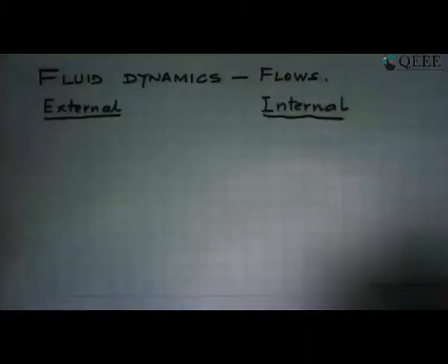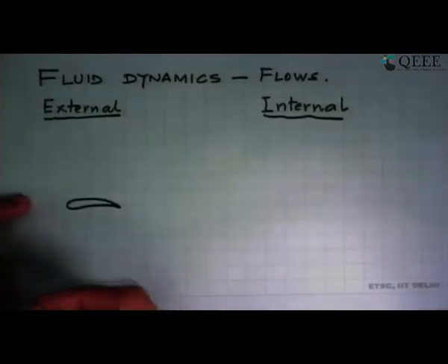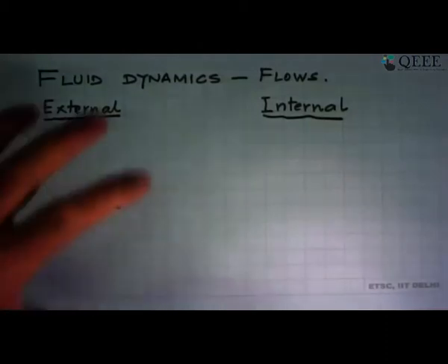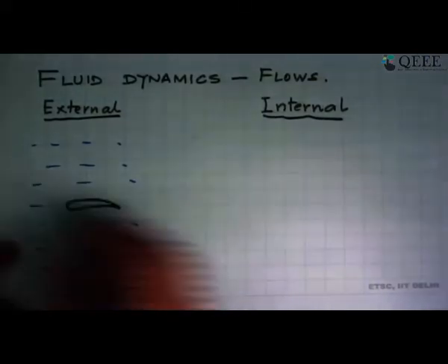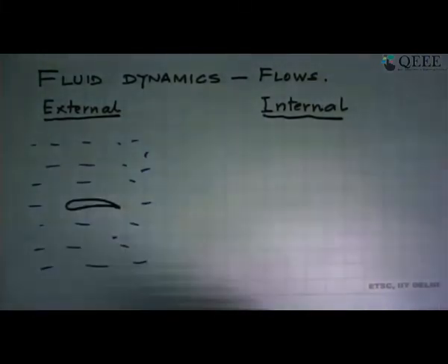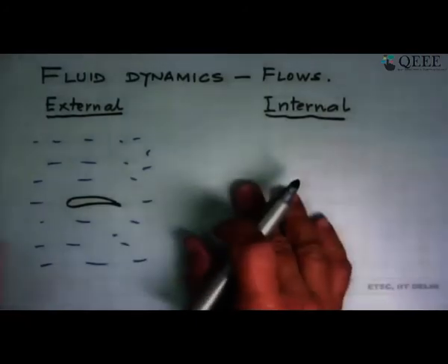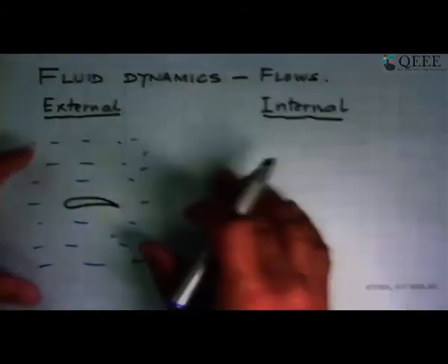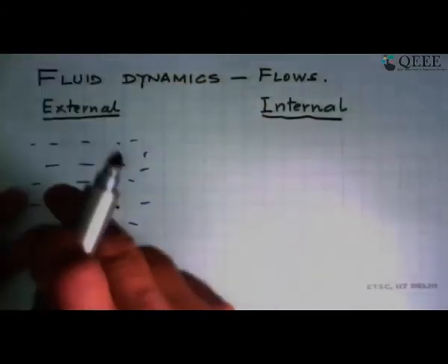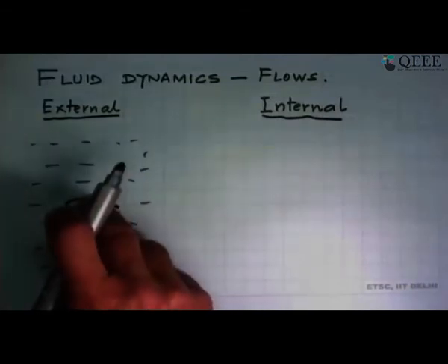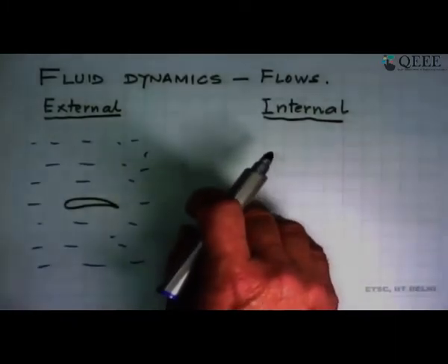What we mean is that in an external flow, we have an object, say an aerofoil or a cylinder or anything, and this is in a domain which has a flow relative to it, where the fluid has no other surface in any other direction. So there are no other surfaces in this problem. The fluid may be stationary. If the fluid is stationary and this is stationary, there is nothing to be done in fluid mechanics. But if it is heat transfer and this surface is hot or cold, we have a heat transfer problem. But that in turn induces a convection fluid flow problem.